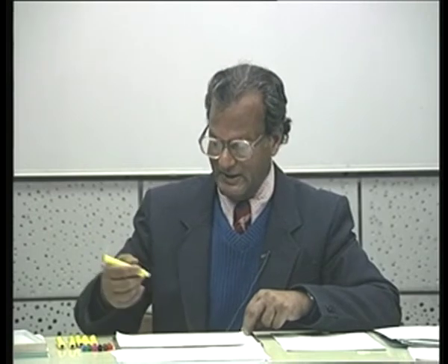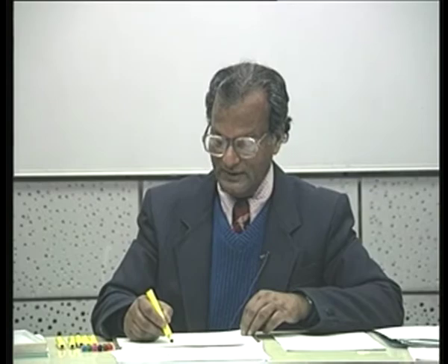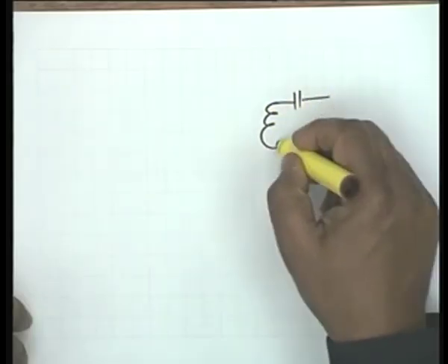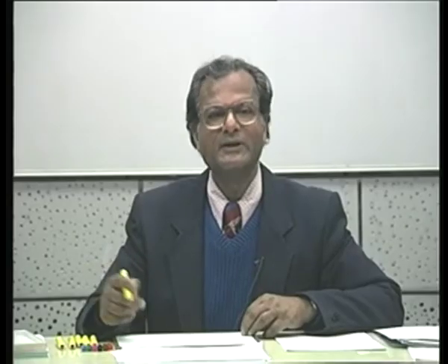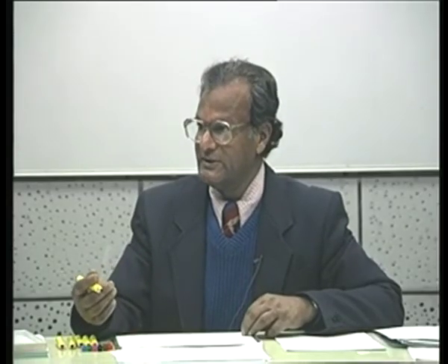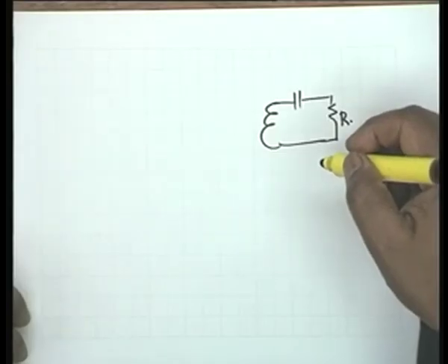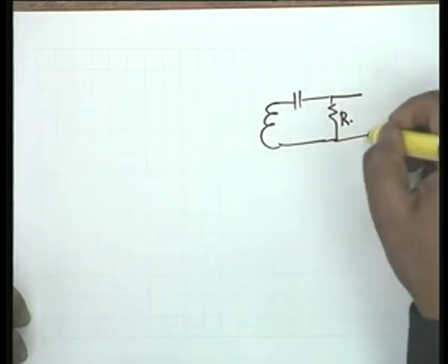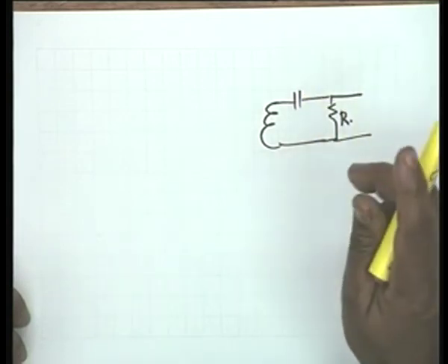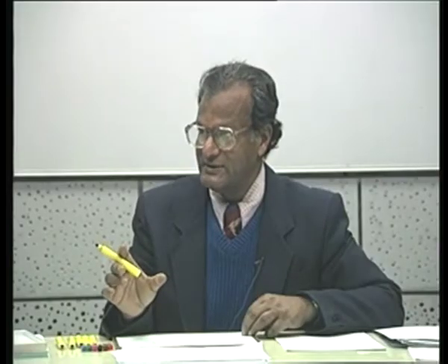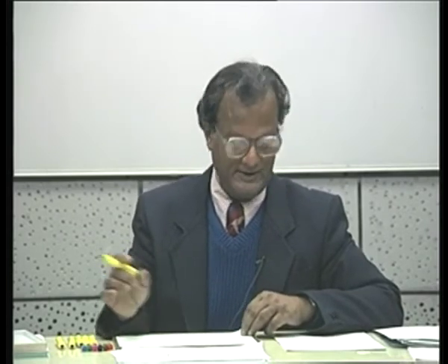It might happen that the secondary has to transfer power to the input of an amplifier stage, where the impedance is basically resistive. So this resistance is inevitable. Then you will have to change your coil and capacitor to adjust to the particular band of frequencies and the sharpness of resonance that you desire.